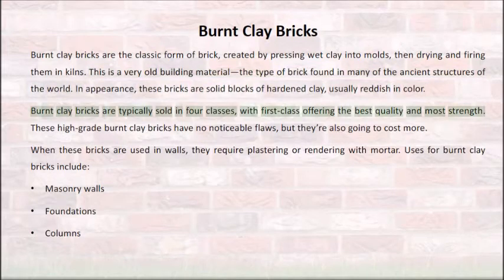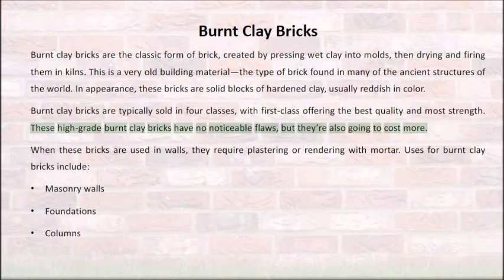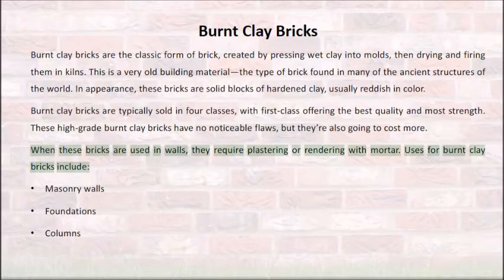Burnt clay bricks are typically sold in 4 classes, with first class offering the best quality and most strength. These high-grade burnt clay bricks have no noticeable flaws, but they're also going to cost more. When these bricks are used in walls, they require plastering or rendering with mortar.